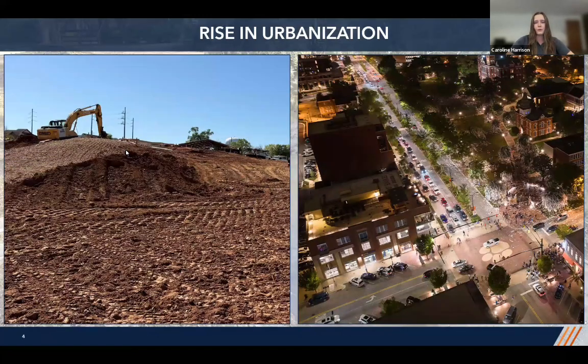Pollutant loading in these water bodies can really be attributed to the rise of urbanization, which causes increases in construction activity, and also impervious surfaces. Our construction activities are really susceptible to erosive forces due to activities such as land grading, excavation, and vegetation removal. As a result, we have a lot of exposed soil, which can be displaced by rainfall. These dislodged soil particles can then be intercepted by our stormwater runoff and then carried off-site.